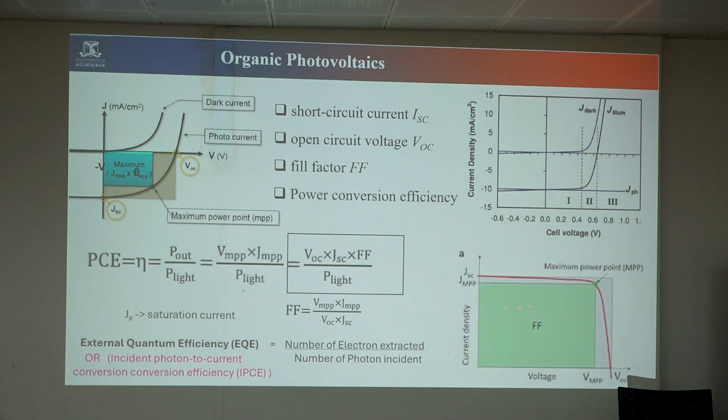We divide the maximum inner square by the outer maximum square and get a ratio. That's your fill factor. Ideally, we want the curve like this, and the fill factor should be 1, but no device gives a 100% fill factor. Okay. So note down these things. We go through some of the questions.